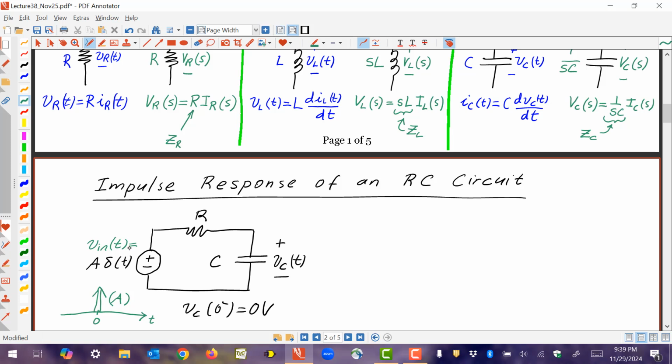But typically what we do is we just take the circuit and we draw the Laplace transform equivalent of the circuit. So the resistance becomes our resistance, because the impedance of a resistance is in ohms, right? So in this blue circuit, all elements have to be impedances. So the capacitance becomes 1 over sC. The voltage vC of t, this is like our x of t, right? Becomes X of s. So we write capital V C of s.